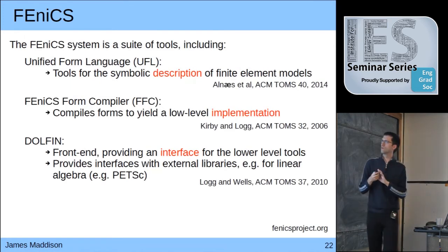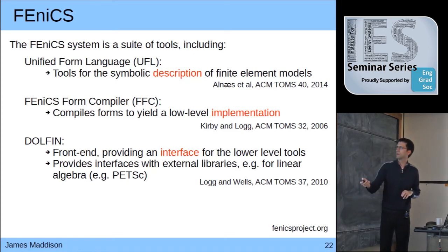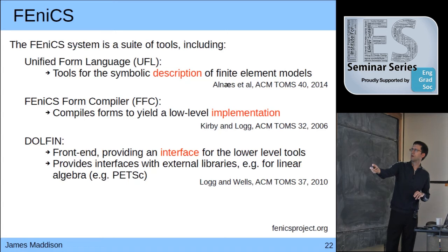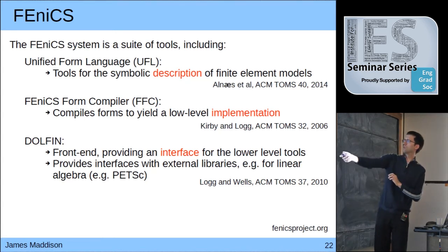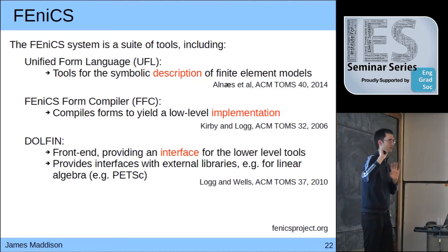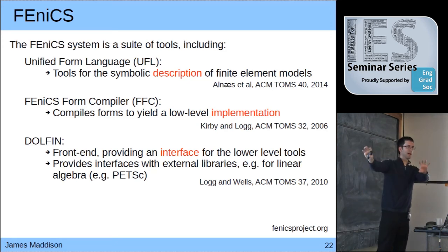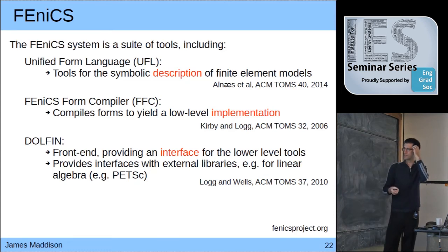So the specific tool that I tend to use, so there are a few different types of tools around, but the one that I've been using for a few years, it's called the FEniCS system. So here's how it broadly breaks up. You introduce a new language, it's called the Unified Form Language, that lets you write down a finite element code, and then there's tools that turn that into working code for you. Actually C++ code in the end that you get out. I want to write down my mathematics, it deals with it and generates the C++ code, and specifically for finite element models in this case.